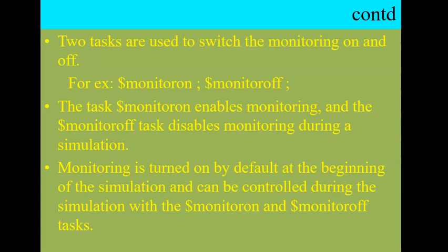Verilog provides two tasks related to this monitor: $monitoron and $monitoroff. The task $monitoron will enable monitoring in a simulation. Whenever I wish to stop or disable monitoring, I can use $monitoroff. Monitor on, monitor off.